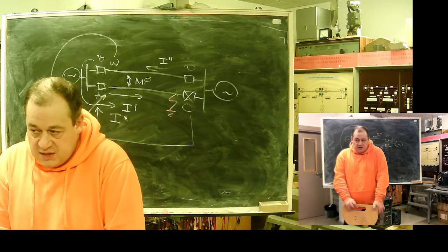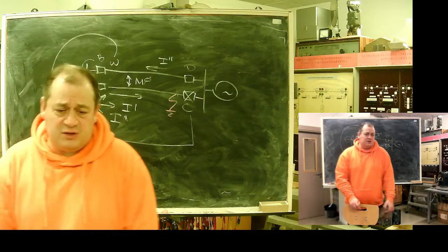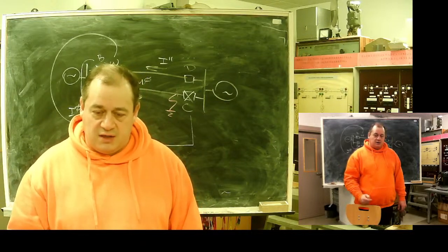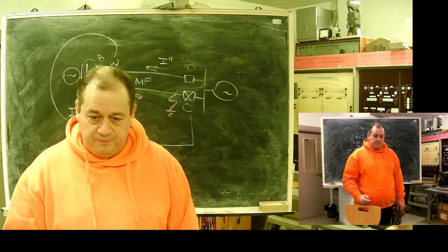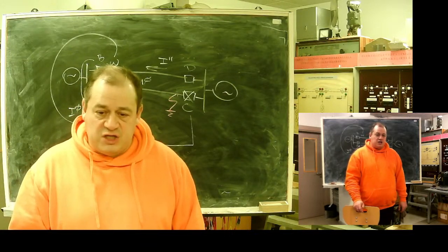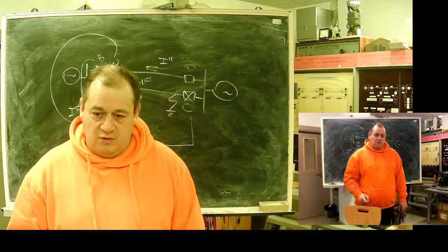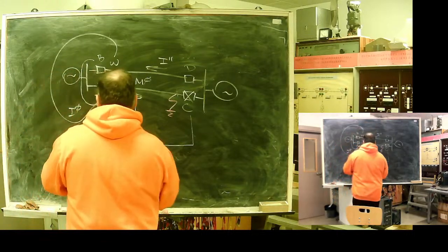Good practice is to take a control record, oscillogram, from an outside fault, any fault, and check the correct sign of compensation. Be careful.